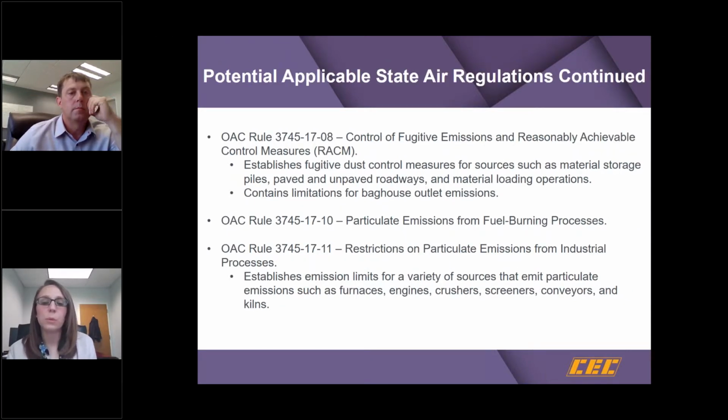1708 is another common rule for particulate emissions, and this is for dust from processes. So we're going to be looking at material loading operations, and it also contains limitations for baghouse outlet emissions. And then the next 2: 1710 is for fuel burning, so you're talking boilers. And 1711 would also be processes, so furnaces, engines, crushers, screeners, and conveyors.